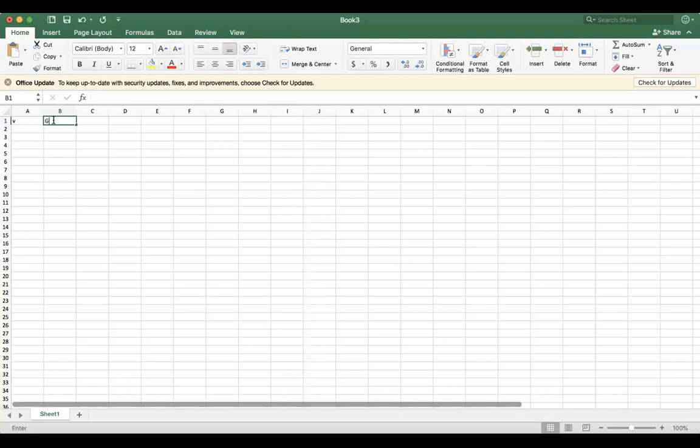Okay, so you have a list of F_D versus V, right? Your velocity data, your drag force data, you enter them, right? For number of filters, 1, 2, 4, 7, 10, you fill out these columns, and then you need to make two new columns for log of V and log of F_D, because you're plotting the log, not the variable itself, right?